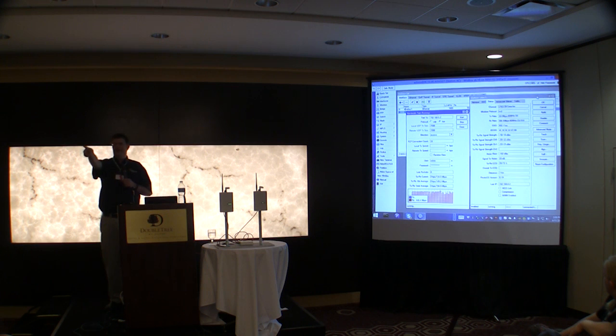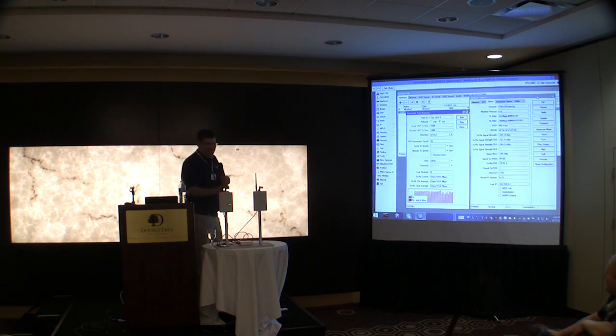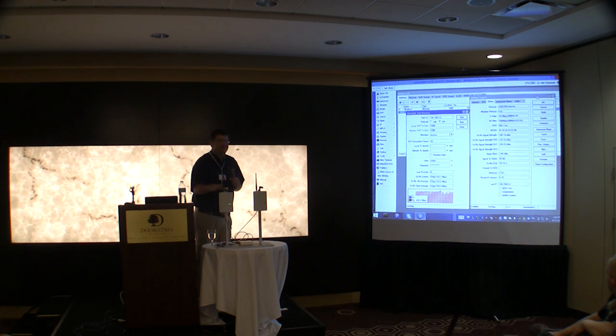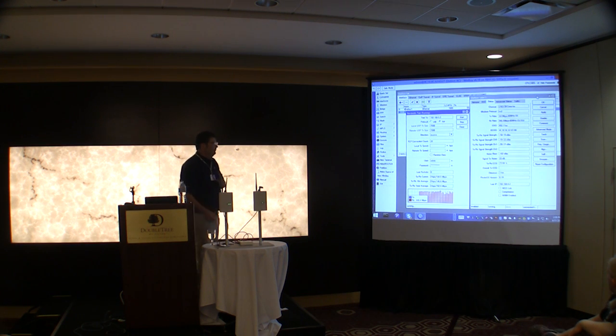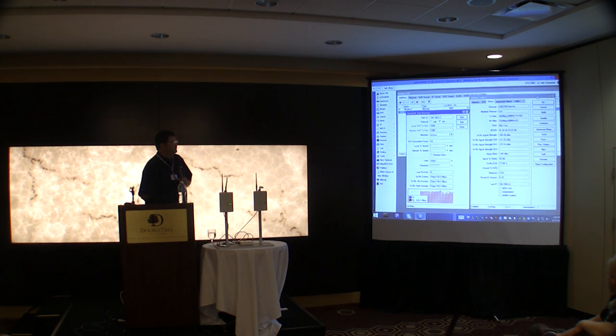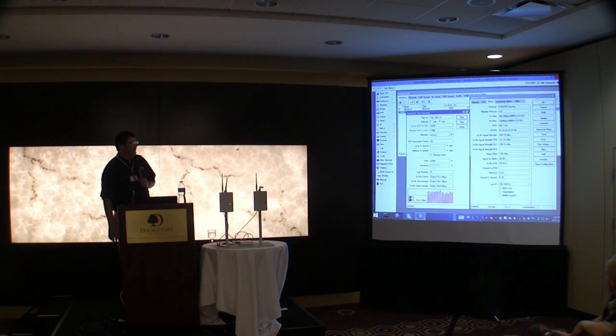Another question way there in the back. Now, let me show you something too. So this is running, and I've got what I'll call an ideal polarity, vertical and horizontal. If we change one of these antennas, we just pop it up a little bit, you can actually watch our signal on one end drop. Now we're down to, yeah, it drops considerably just by changing that to that slant polarity. Now we've changed our isolation between those two antennas, and we have a significant drop in performance.